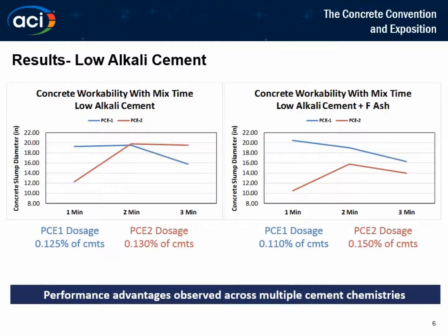So I really wish that Tom Vickers was here, since he actually ran all the experiments and could explain it better. But in theory, to explain the drop-off, workability retention and dispersion are essentially opposite ends of the spectrum. So I would interpret that as you have fast dispersion. You can't have both. If you're delivering highly efficient PCE binding, you have fast dispersion, you're consuming that, and it's not staying in the system long to maintain workability.